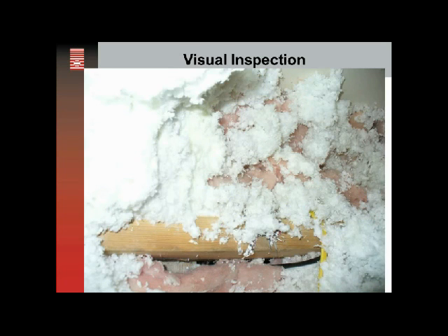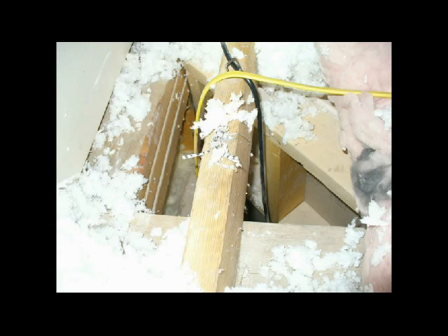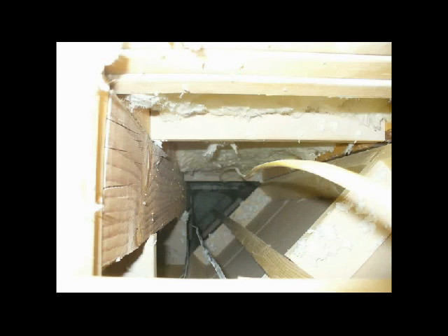But it's a classic shot up in an attic: see something suspicious poking through the insulation layers, and if you dig out, you can find a nice little bypass or an air leak that essentially connects the living space to the unconditioned space or the vented attic. Another shot looking down into the crevasse of the bypass, and in the wintertime you can warm your hands on these things.